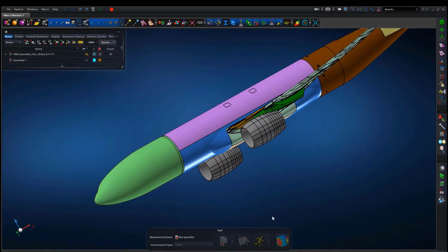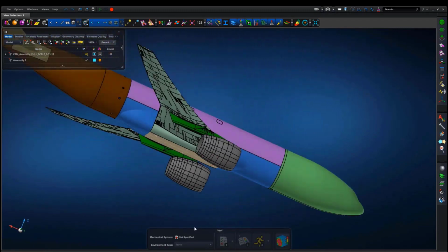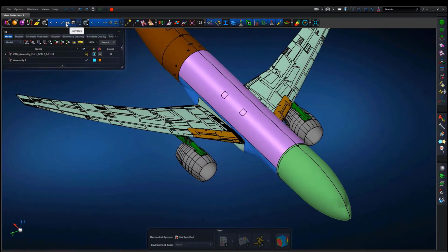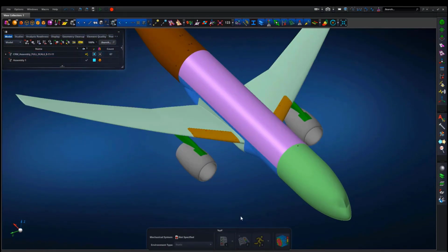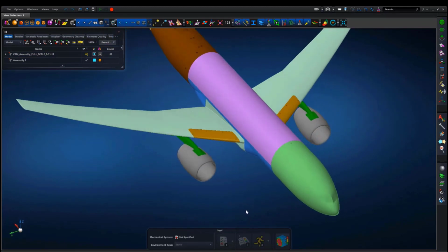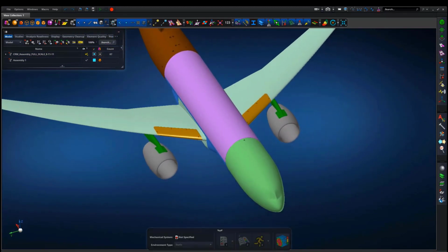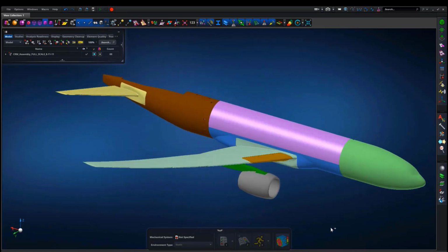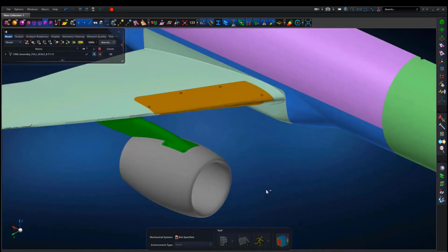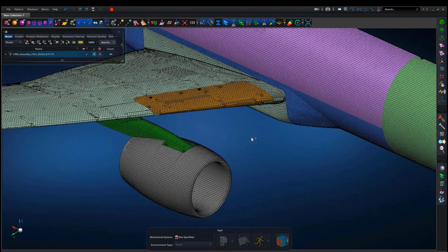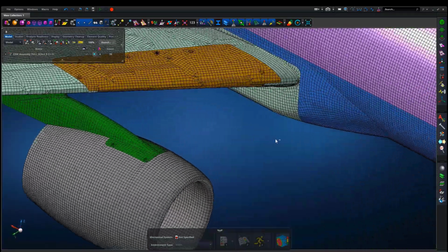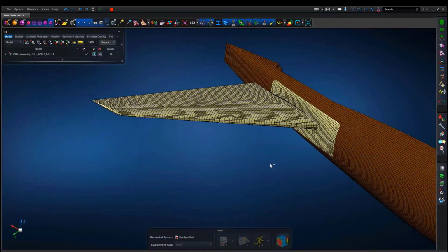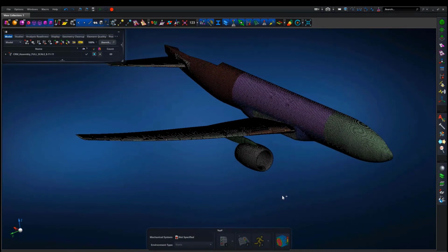Now, let's do the same thing, but with variable pressure load. Let's say just for kicks, you're working on a new aircraft design, and either you or someone on your team just completed a CFD analysis on your new aircraft model. The next step is you would probably take that output from the CFD analysis and map it onto your FEA model in order to do a full structural analysis, maybe an internal loads or something like that, thus being able to certify your new aircraft design. So that's the workflow we're going to do here.